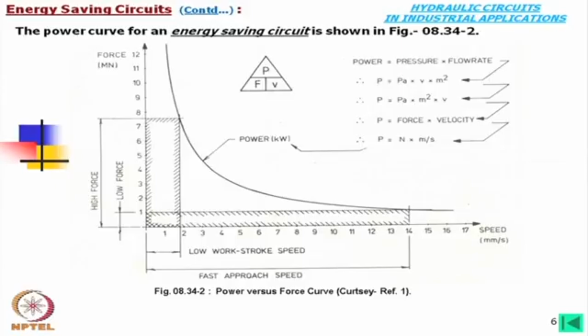If we study one operation cycle, we know what the speed is, what the flow is, etc., and from there we can design our systems. We can have, say, in a discrete manner, these are the flow, this is the pressure, and from there, by averaging, we can select the motor, pump and required components.